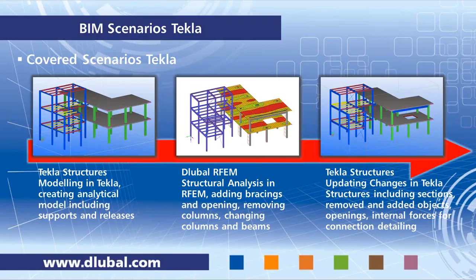And as with Revit, we can also get this analytical model, do the structural analysis inside RFEM and update changes. So it's more or less again a round trip, but at the same time you can start with RFEM and only end up in Tekla, and so you have a one-way direction. Also here we have update capabilities.